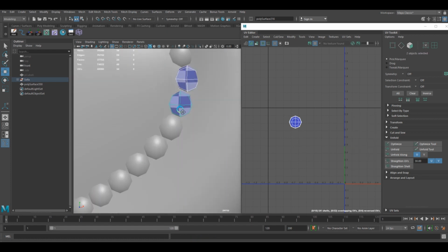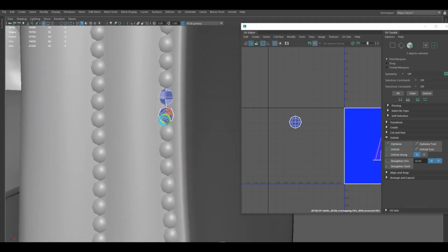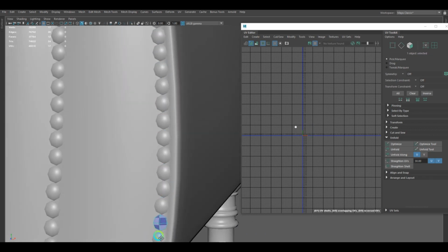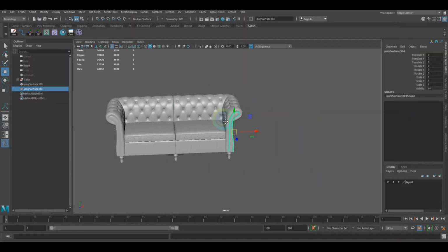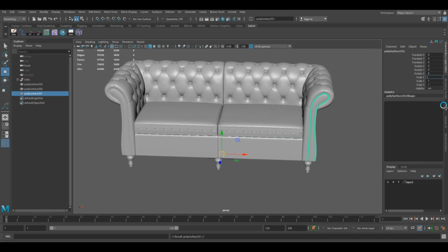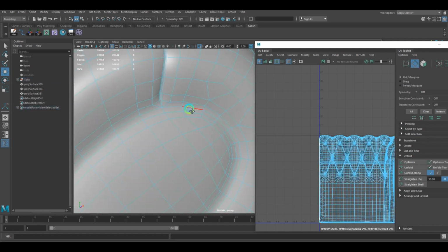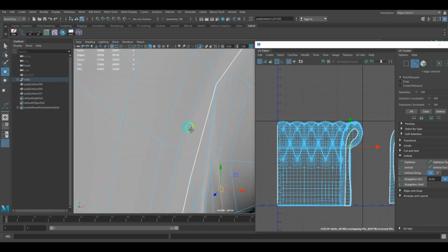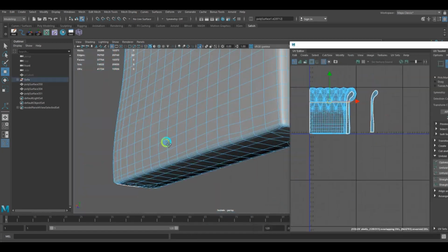Once I applied the transfer attribute option, I only select the objects and press G on the keyboard to repeat that process. Once done, I am flipping it to the other side. For this object, first I did planar mapping from the Z-axis, then I am giving cuts in the UV where I want it to unfold properly.